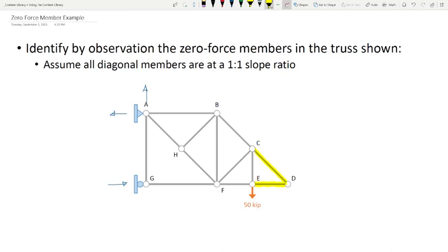Okay. Anybody see another joint that we ought to focus on? We looked at joint D. Let me circle that. What about now? Any other joints that we ought to look at? G. Okay. So you're asking me to look at G. Why are you asking me to look at G? Well, the Rule 3 or 2, we can quibble on that, but what member are you looking at? What member screams out zero force member to you?